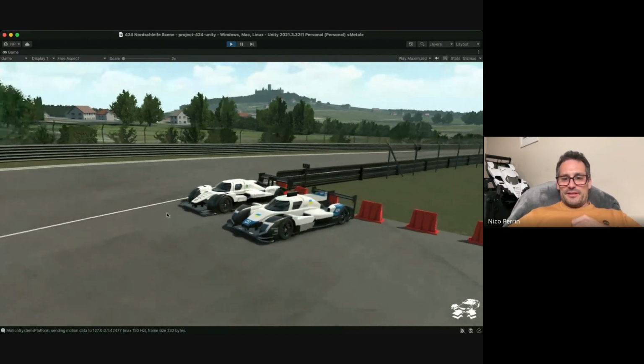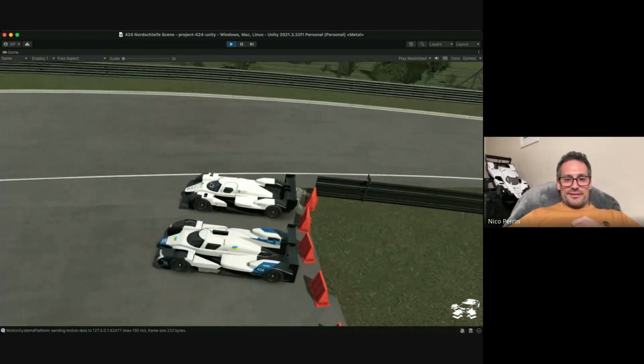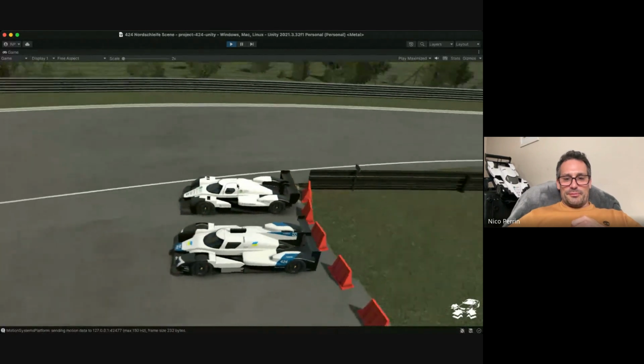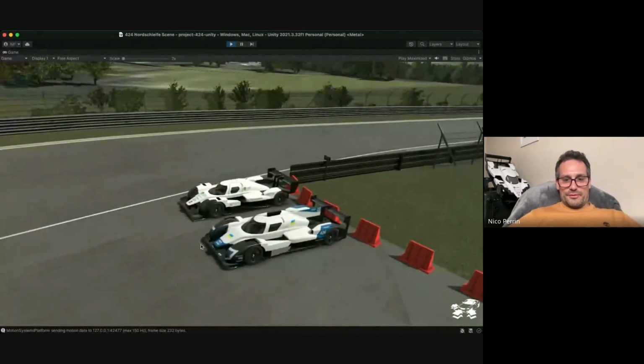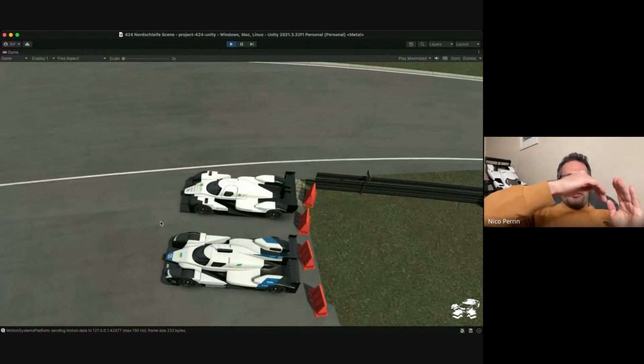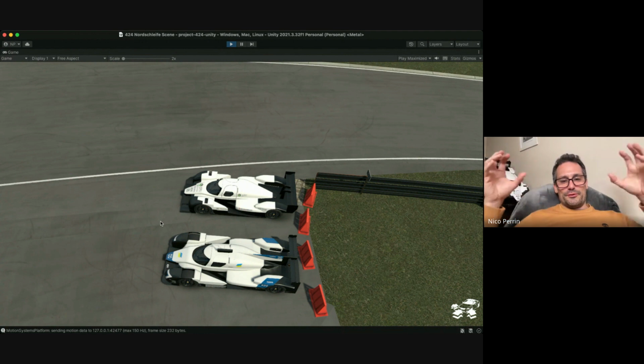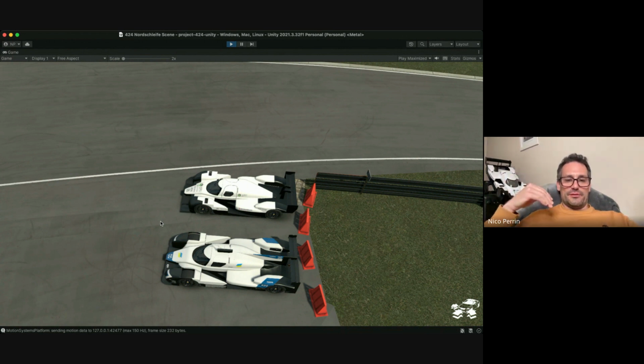So we're into Unity, our dynamic simulation software. And we left the LMP1 car on the side. This is now the car that's driving the Nürburgring one. But I like to use this just to explain what we've done in 2022. The main goal was to go up on the polar of the car, which was increasing the drag level. Think about it as going from Monza in Formula One to going to Monaco. So we needed a 30% or even 35% increase on the drag of the car with the associated downforce and more. The Le Mans car was still under the regulation of Le Mans.